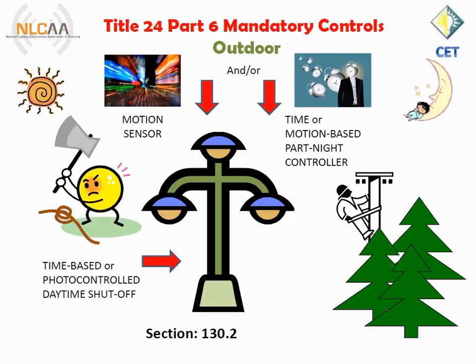Outdoor lighting must be out within 99 minutes after sunrise to pass acceptance testing. That is changing for 2016, but remember, we're looking at the current code and the current acceptance testing criteria. And right now, sunrise is considered to be official sunrise at your geographical location plus no more than 99 minutes.